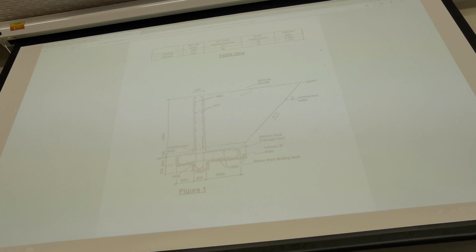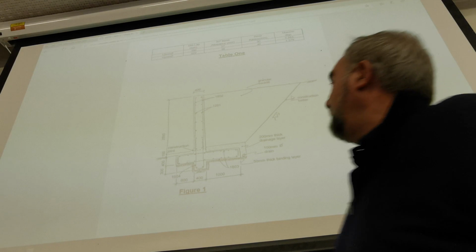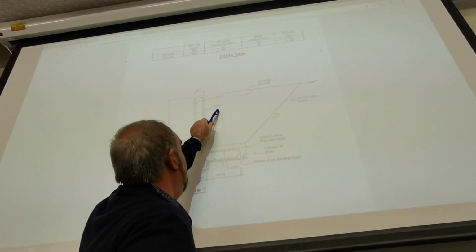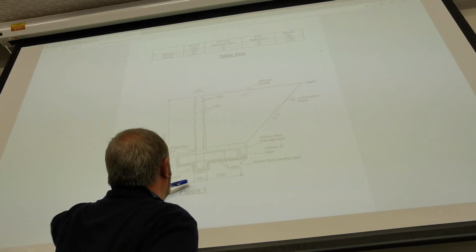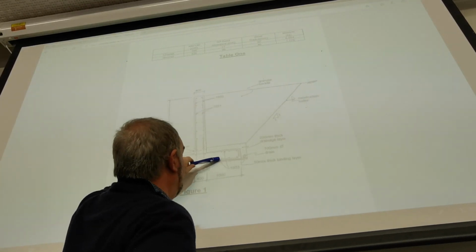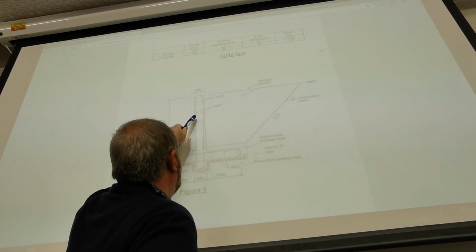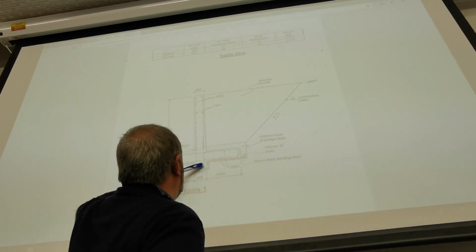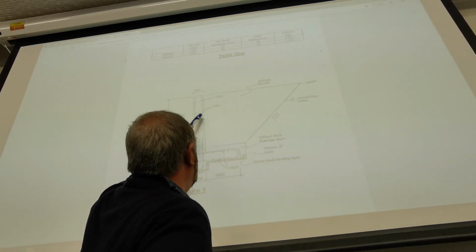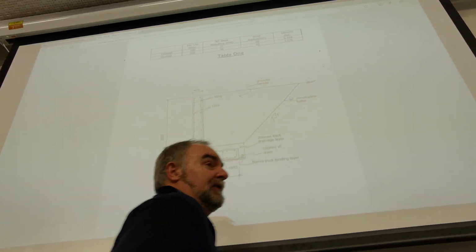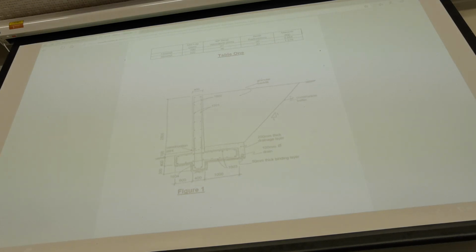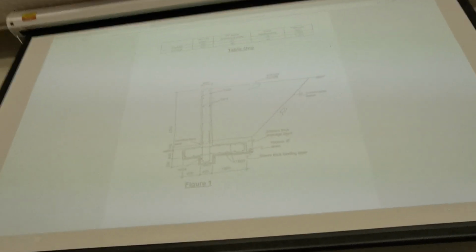Now we talked about bar marks in the lecture. This is on Moodle, by the way. If you're wondering, you can't see it very well, you can bring it up on your monitor. If you look at this first bar, number 01, 02, 03, and 04. Notice 03 is on the top and the bottom. 01 and 02. The 01 is all these dots everywhere, or donuts, and 02 is the bars that come down and touch on the construction joint. So we can write that down. First up, we can go 1201, 1602, 1603, and 1604.